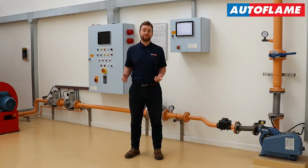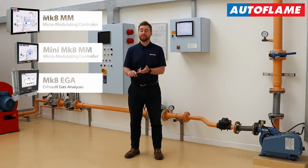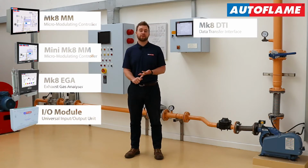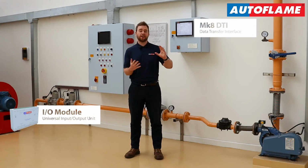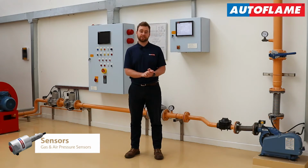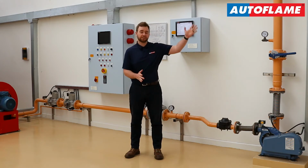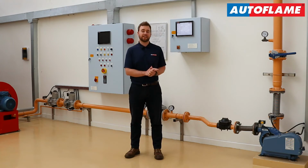So of course you can take inputs from your MMs, EGAs, the DTI itself, of course your input-output modules as well, but now we can take inputs from various gas and air pressure sensors. For example, let's say we've got a gas sensor in our main gas line, we can set thresholds based on that. Same for an air pressure sensor in your boiler room ventilation.